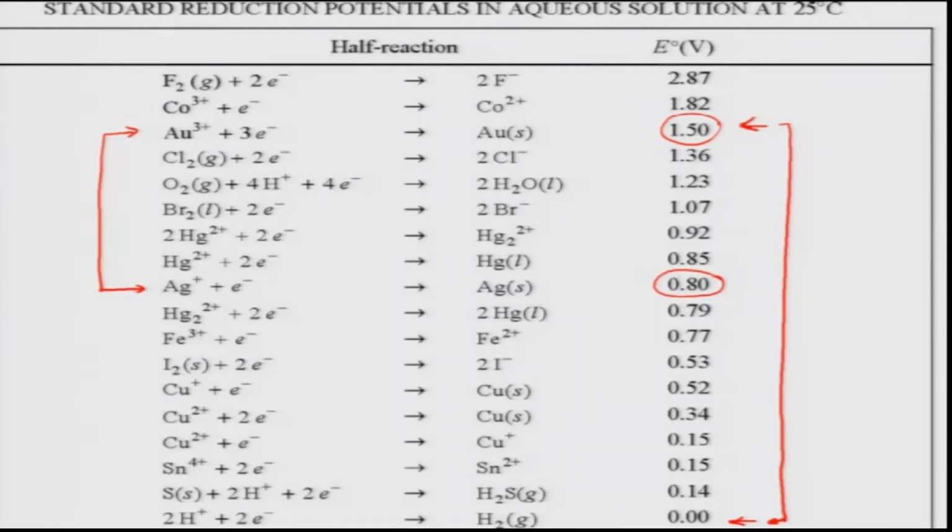So, now if you have a gold silver alloy and we dip it in acid medium, then gold will remain, silver would dissolve, and then we can have a porous gold structure, and the porosity could be in the nanometric range. That is what we call a nanoporous material.